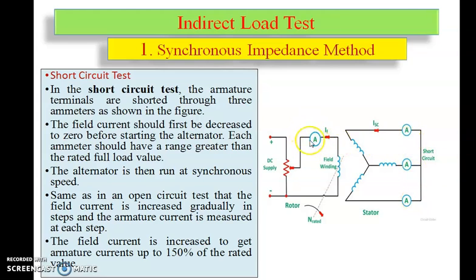Okay, give 0.1 current here, then measure the short circuit current, give 0.2 current, measure the short circuit current, give 0.3, measure the short circuit current. Now I am connecting the 3 ammeters. Okay, so for taking the reading you can take the aggregate of these three. Whatever readings you get from the 3 ammeters you connected, for taking one reading you should take the aggregate of these 3 values. That means you divide the ammeter values by 3 to get one value of current.